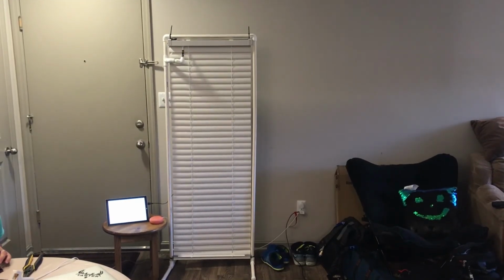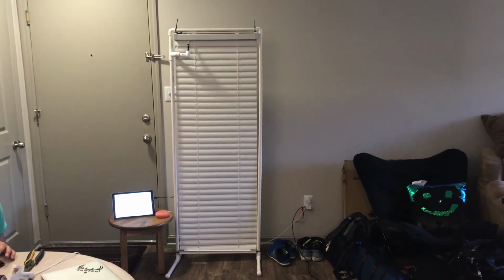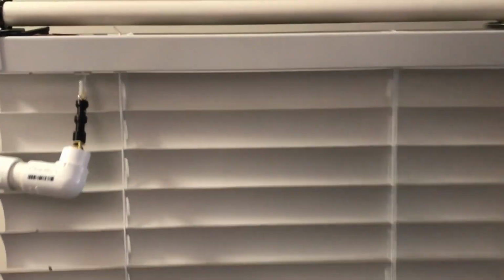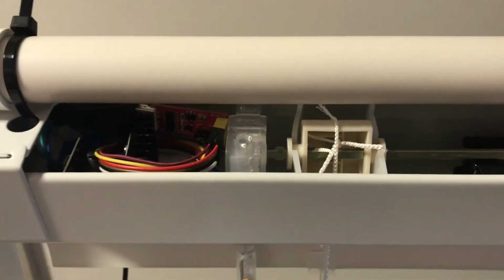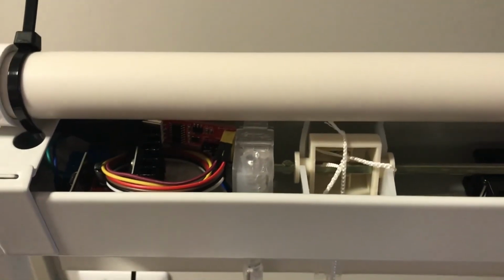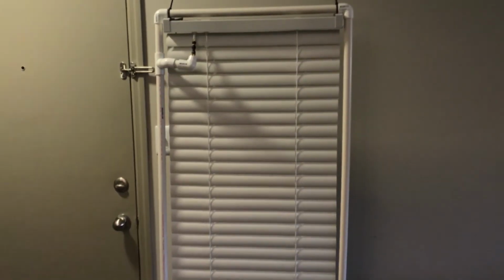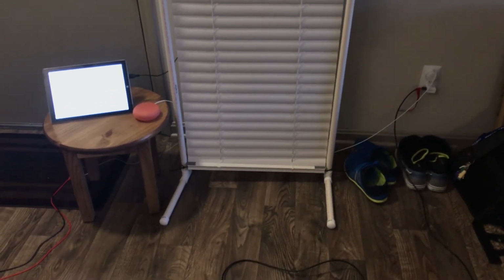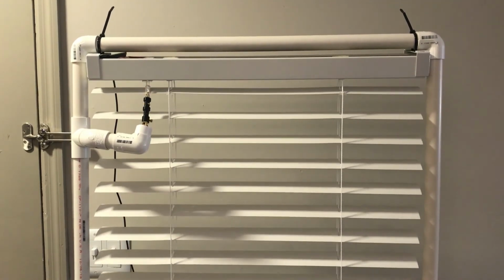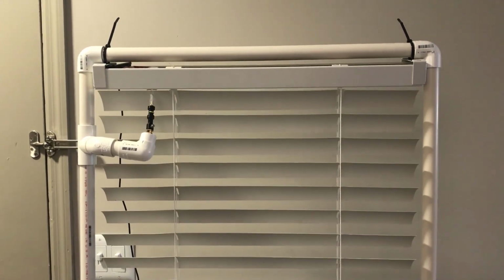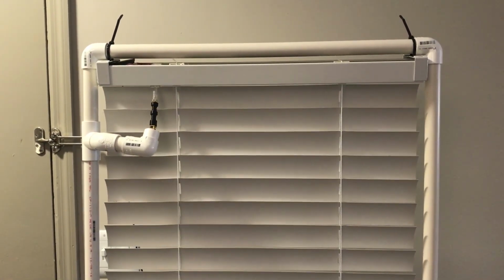This is our Google Home Smart Blind. Our blinds are controlled using a DC motor connected to an H-bridge for power. This H-bridge is then connected to our UART controller, which holds our programming to operate the blinds. The controller also uses a Wi-Fi module to receive commands from the Google Home. This allows users to ask Google to open or close the blinds to their desired level. Now here's Andrew with our demo.